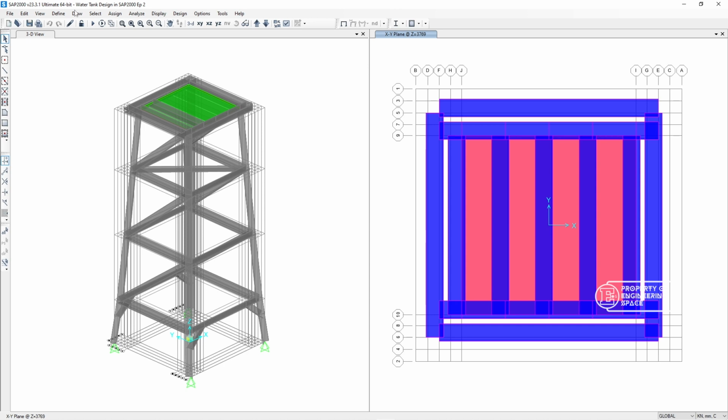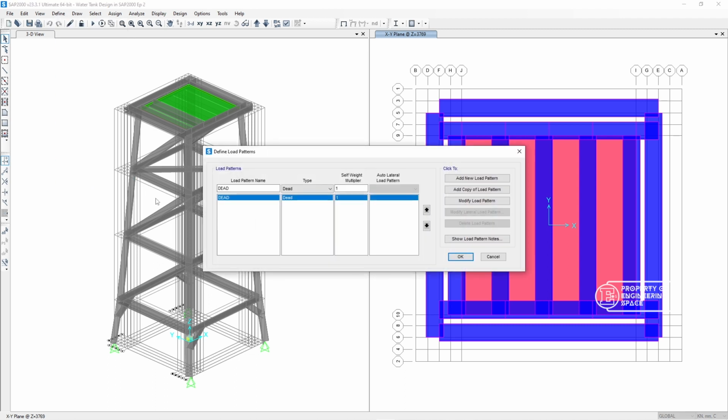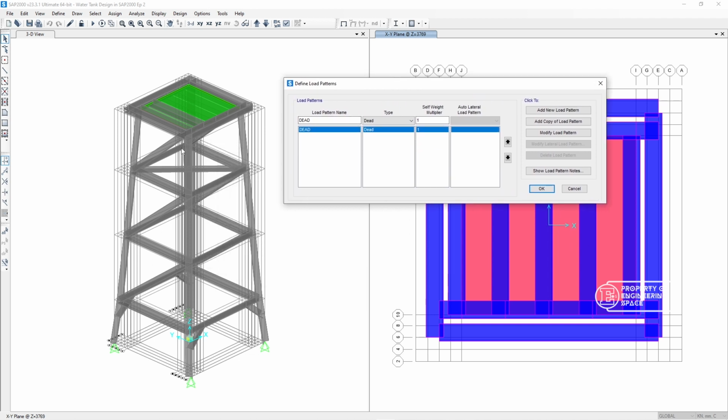Once again, what we need to define next is the load patterns. Load patterns mean what cases of load we're going to give to our object geometry or our structural design. So basically I will give you a simple load pattern that meets the Indonesian load standard.